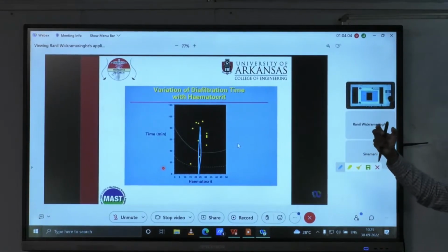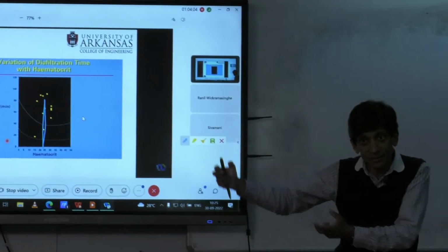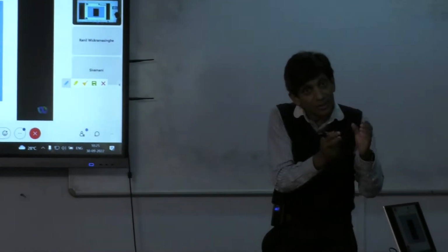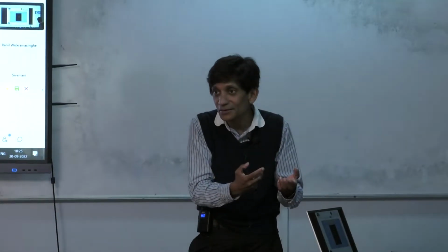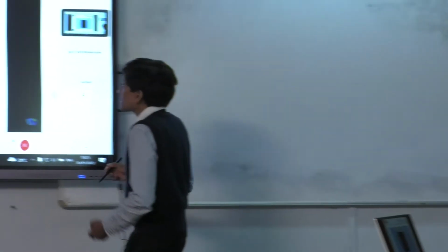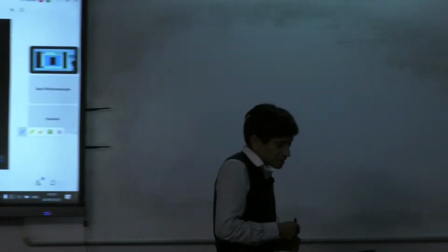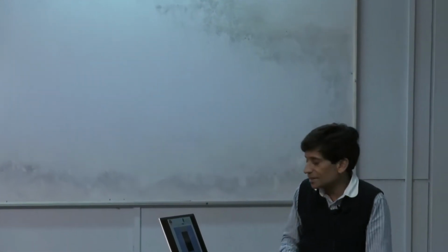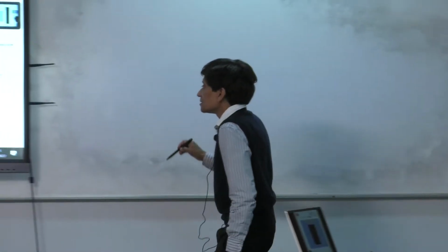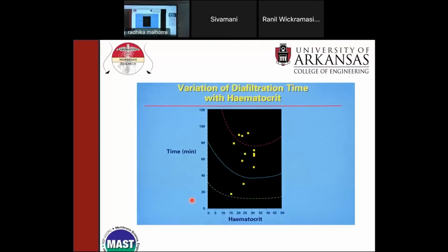Because on the one hand, you have a very large diluent, high flux, but it takes a long time to process all that diluent. On the other hand, only a small amount of diluent, low flux, but the time is less again, okay? But at some point, there's an optimum, okay? And in fact, you can show that this optimum is the wall concentration divided by e. If you're interested in the analytical solution, let me know, and I can email you the way to do it, or email you a paper. There are a couple of papers, and our paper also calculates it, okay?